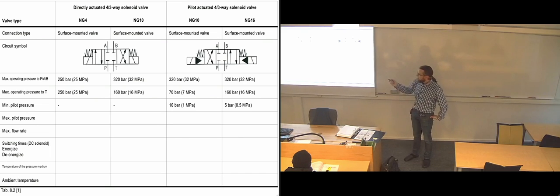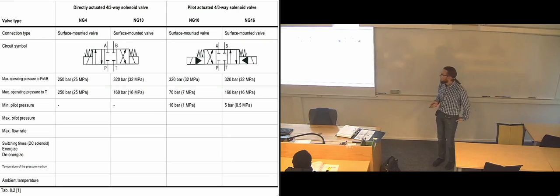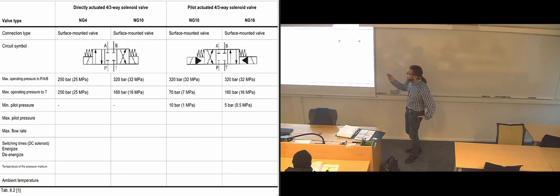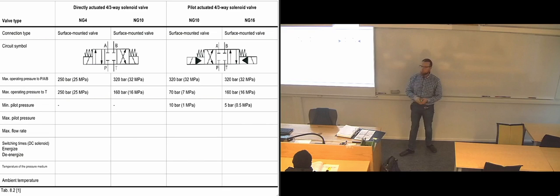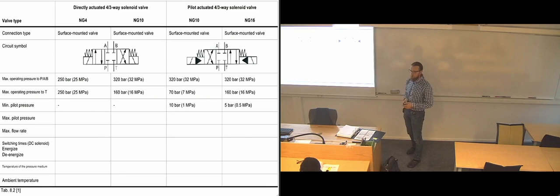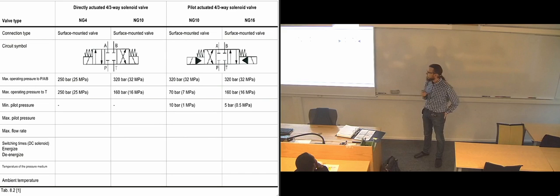And as you can see, the pilot pressure is very small. You don't really need much pilot pressure in order to activate those. And that has to do with these being slide valves, because sliding the valve back and forth doesn't really take much pressure. So long as you don't have a super strong spring there that's going to put a lot of force into it, you don't really need all that much pressure in order to push it in either direction and compress the spring.